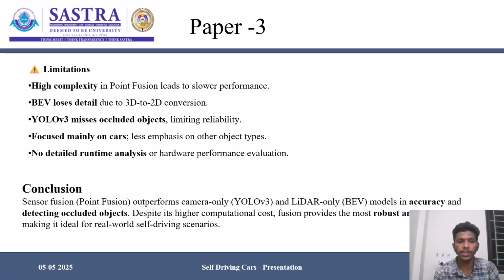The limitations of this paper are that sensor fusion using point fusion has high complexity. For the lidar data using the BEV model, it loses some details due to the conversion of 3D to 2D data. For camera based detection, YOLO V3 misses some details, and it has some lag issues when we perform this evaluation in hardware.